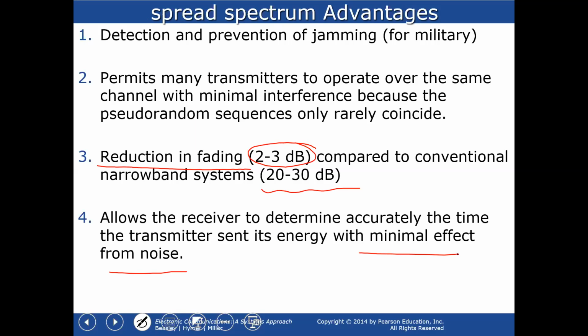We said that we use two techniques, frequency hopping and direct sequence spread spectrum, and both of them use what we call the pseudo noise code. The pseudo noise code depends on generating random data. The main difference is that in frequency hopping, I'm generating a random carrier frequency. In direct sequence spread spectrum, I am creating random pulses to be modulated with my signal.